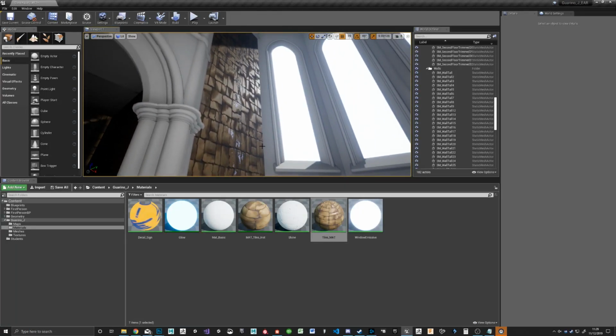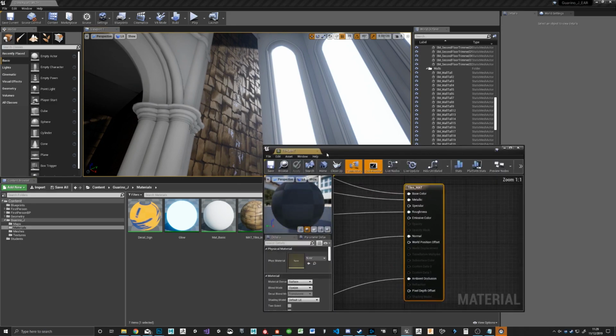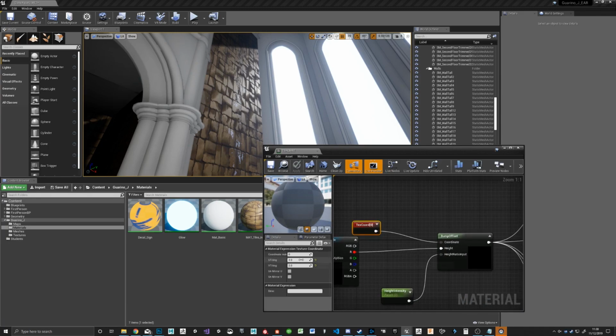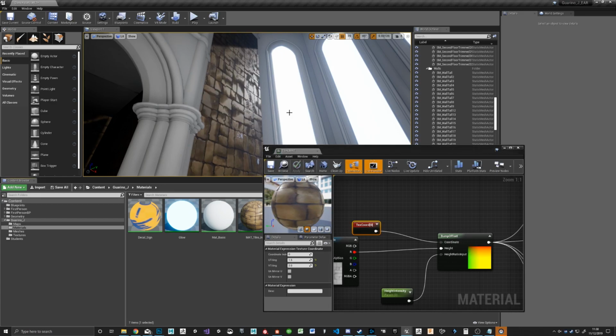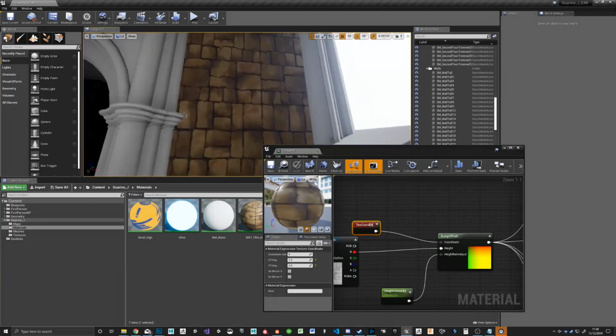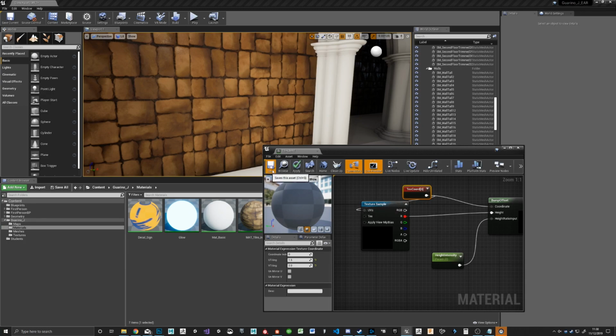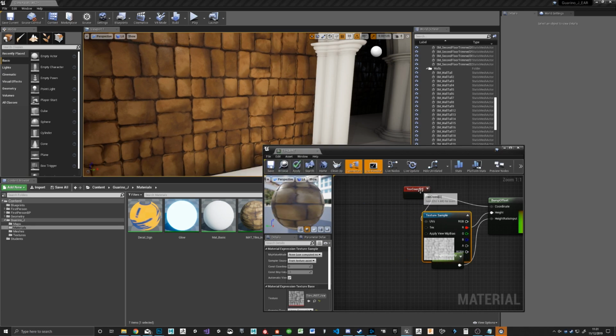And let's say it's not stretched out enough. They don't have to be uniform on the U and V. Let's say our U should probably be 1.5. Hit save. Don't forget to plug your coordinate into your height map, otherwise they'll be unaligned.